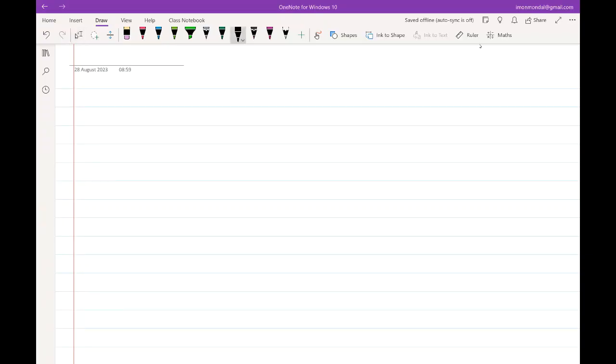So in the previous lecture, we were starting to look into the effects of, particularly we were trying to look into what happens if we increase the size of the device. So why did we want to increase the size of the device? What about R naught? In order to increase R naught, R naught is directly proportional to L, GDS is inversely proportional to L. So if we have to get a high output resistance, we wanted to increase the length.